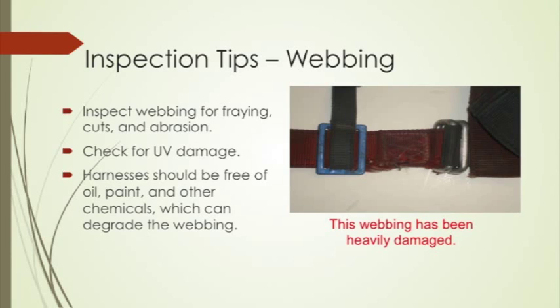It is suggested that you do not write directly on harness webbing. Names should be written on the label. Some inks cause materials to weaken. Manufacturers have different requirements for broken stitching. Be sure to consult your equipment manual.